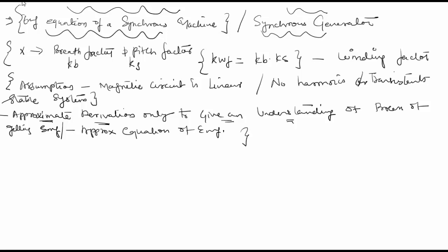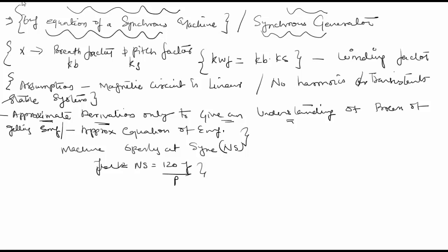These are some of the things I want to highlight. Again, I assume that the machine is operating at synchronous speed. The synchronous speed is given by ns is equal to 120 F by P, and the frequency considered for the EMF generated is 50 Hertz.